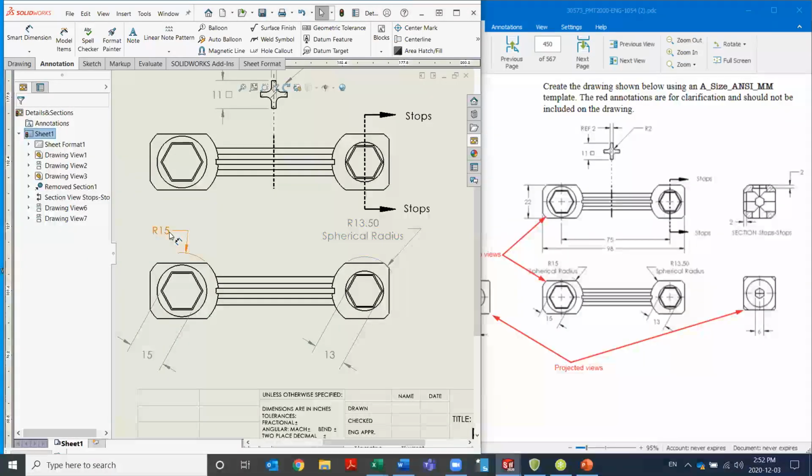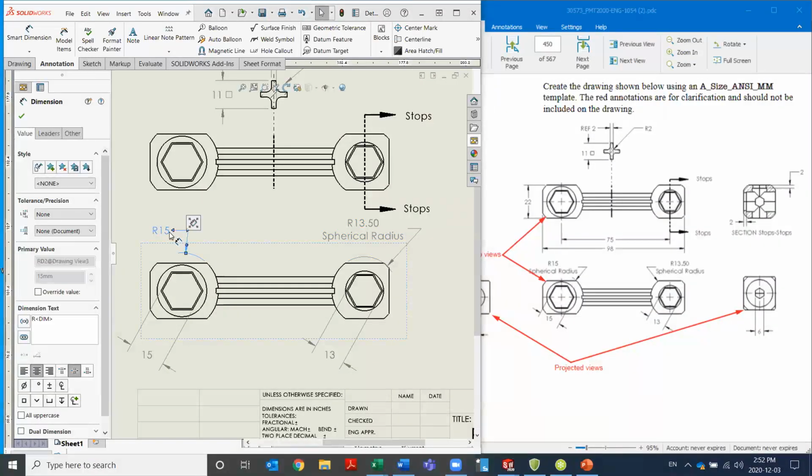And I'm going to do the same thing here. And there's my view palette. Now, every once in a while, you'll notice that view palette is shy, so it disappears on you. When you're in a part file and you do that, you have to go back to where it was and hit Control to bring it back. In a drawing, it's great because you don't even have to be close. I can be down here and think, oh, I did want to use that view palette. Hit Control down here, and there it is right here for us.